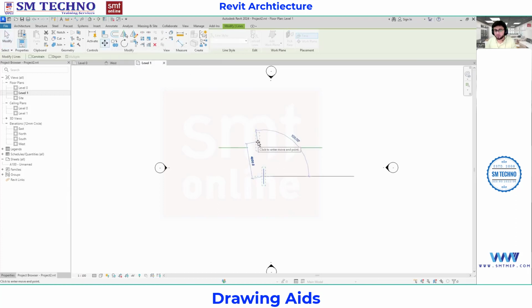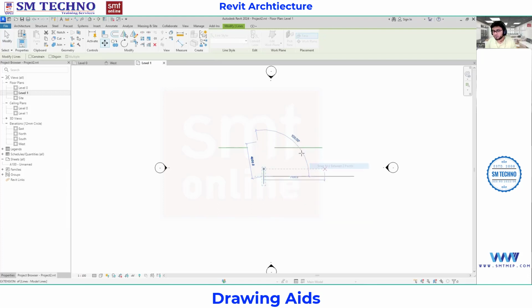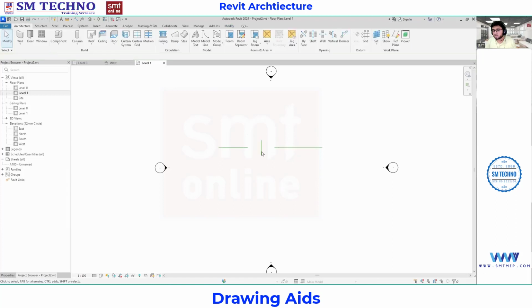When you are going to move from here, just right click and go for the option of snap mid between 2 points. Can you see? Snap mid between the 2 points. Select this point and select this point. Automatically we will get the midpoint in between. Can you see? The line has been placed exactly at the center. So this is called the snap override.